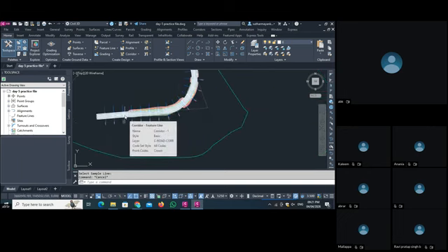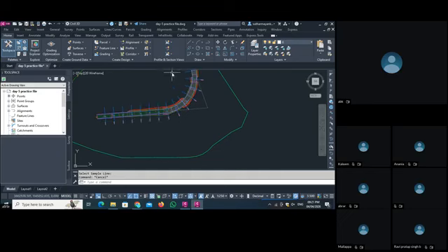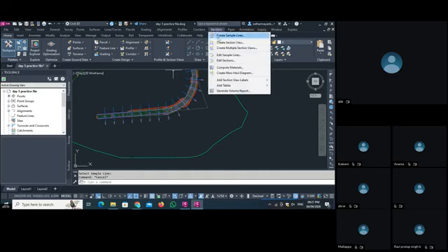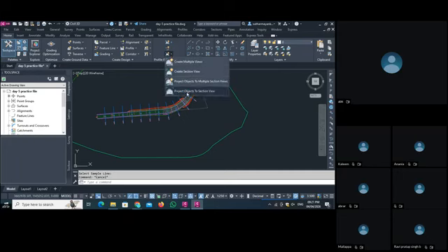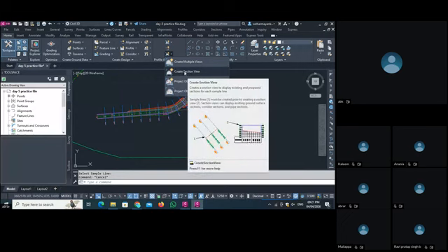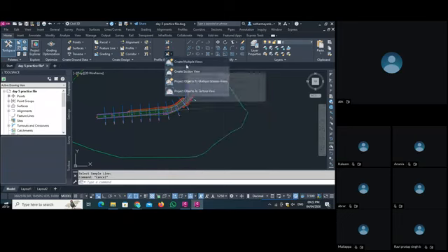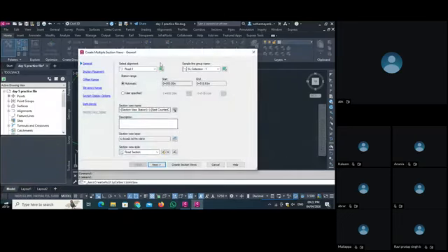And now we go for the, see, when you go here in a section view, you can see create a section view from here. First of all, we select a sample line. Now we go for a section view. Also, if you come here, you can set a section view from here as well. If I select section view 1, I can create a section view for only one sample line. If I create section views for multiple sample lines, as I select, this dialog box opens.